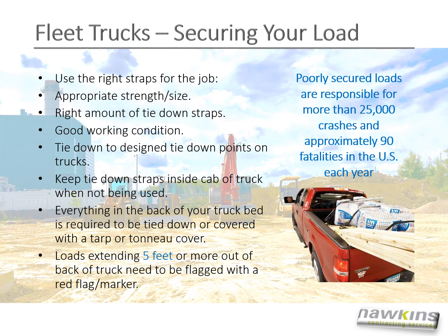Securing your load. Use the right straps for the job, the appropriate size and strength, the right amount of tie-down straps, and make sure they're in good working condition. Tie down to the designated tie-down points on the truck. Keep tie-down straps inside the truck when not being used.